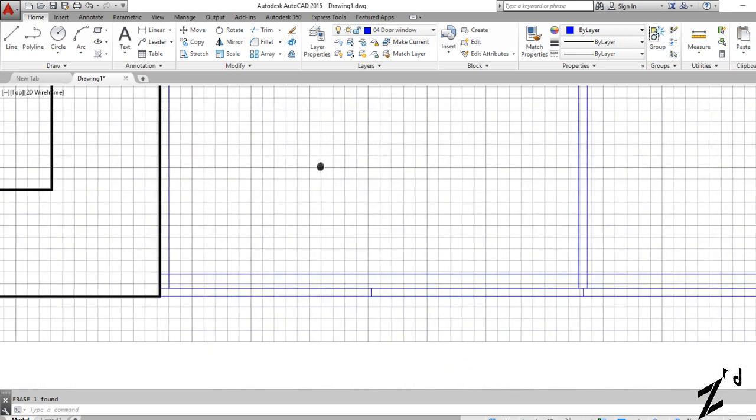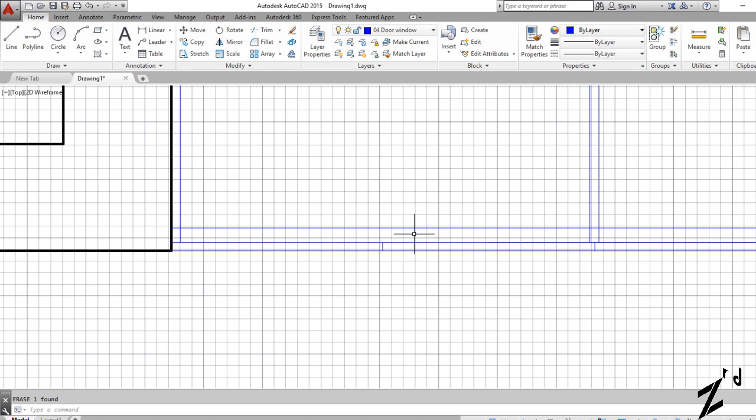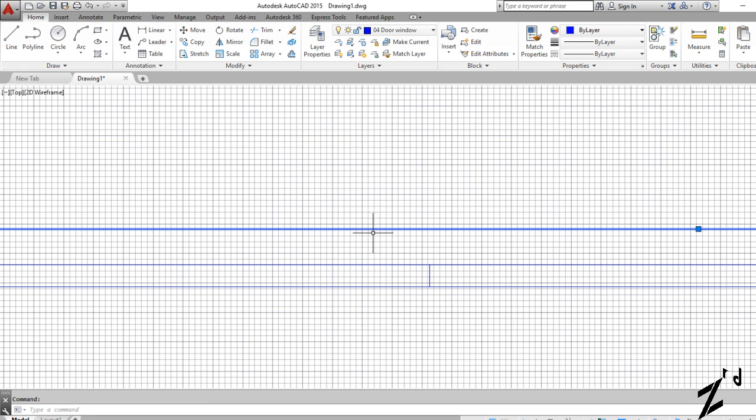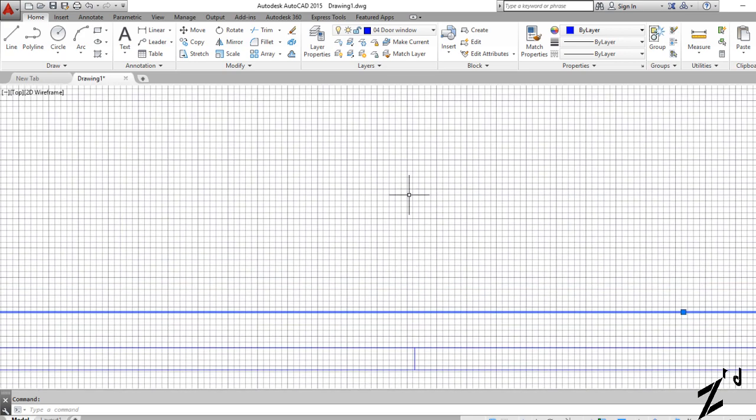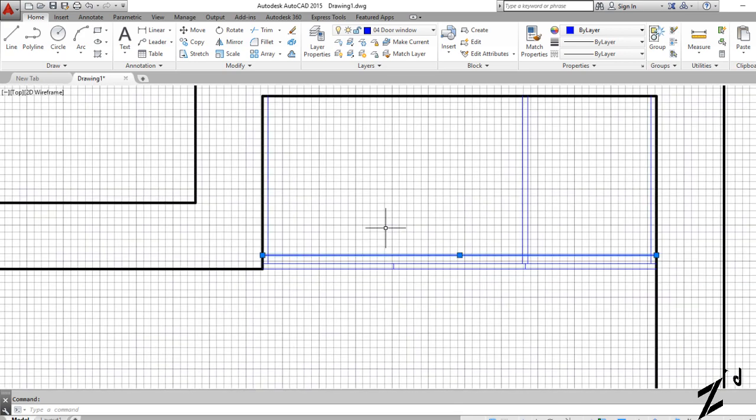And the issue is when you start using things like drawers. The plan and thing of your drawer is that the face, or the absolute front of your drawer itself, can come out only up to this line. After this, you have the handle. If you have a lock and things, the key is going to stick out. So you have to leave clearance for all of that. So that's a good 5-6 centimeters also. And behind that is where the actual drawer will even start, right? So these kind of considerations have to be well thought of, but you invariably realize these things as soon as you draw a single section, right?